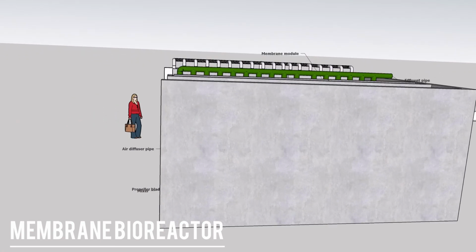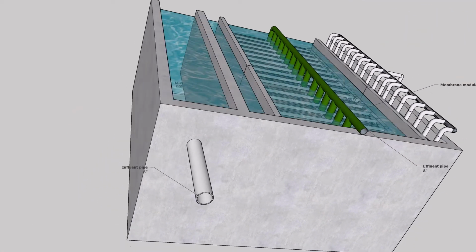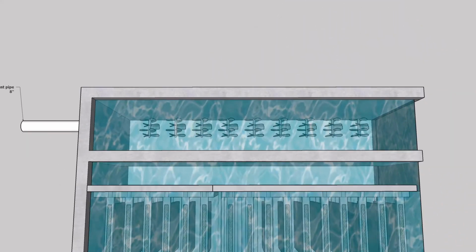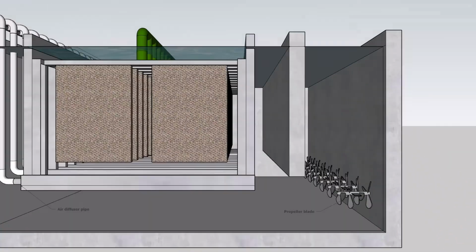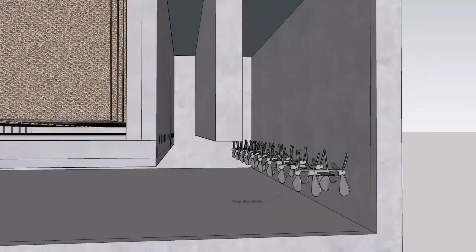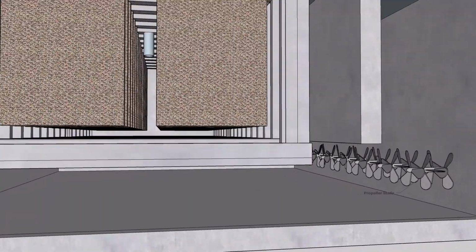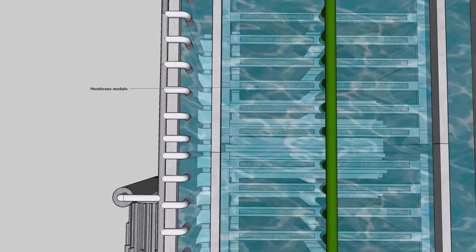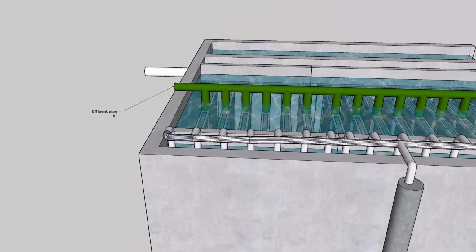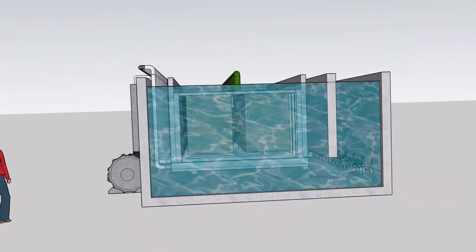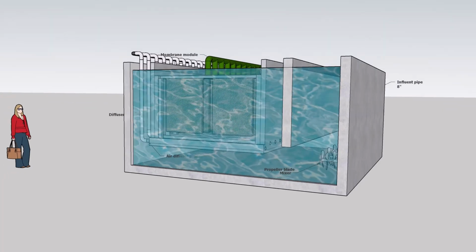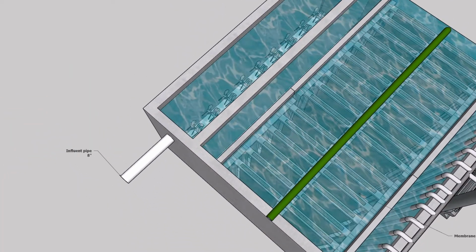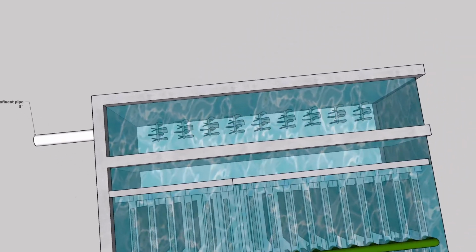The last unit is a biological treatment unit. Membrane bioreactor, or MBR, is a biological treatment unit that has a high efficiency level, which operates through a diffuse aeration system and utilizes membrane components to capture biological pollutants. In short, it filters the water. The advantage of MBR is that it is a compact treatment which does not require a secondary sedimentation tank and can replace the role of a disinfection unit to inactivate the coliforms, and does not require a large amount of space, which is a really good choice for a compact wastewater treatment plant.